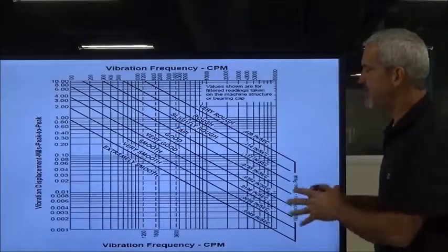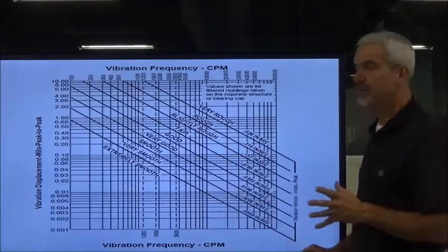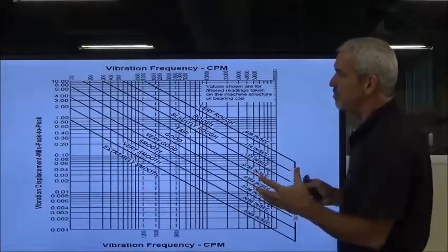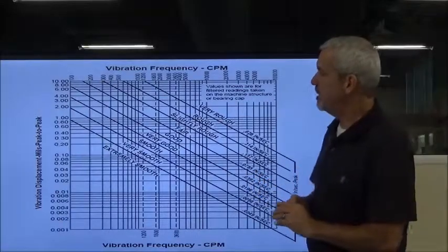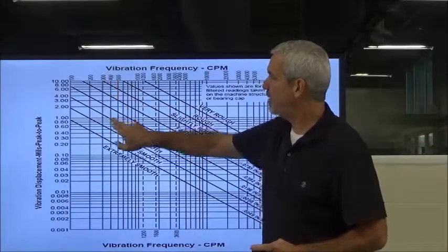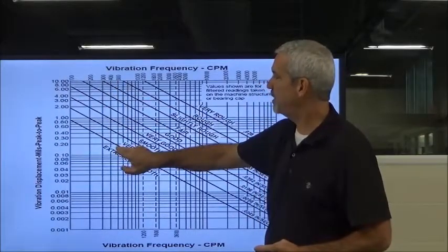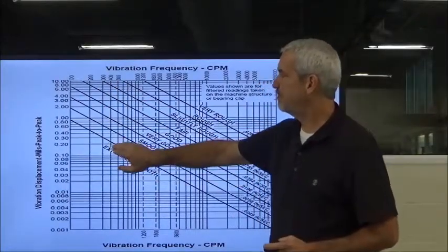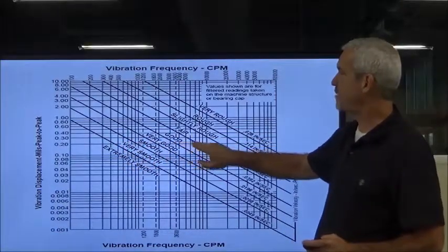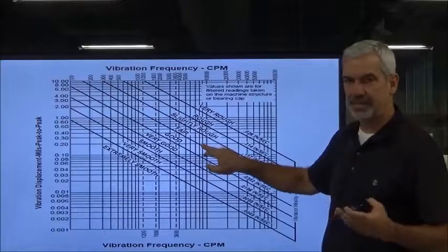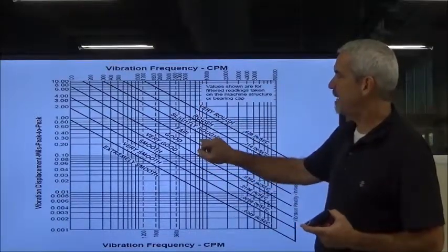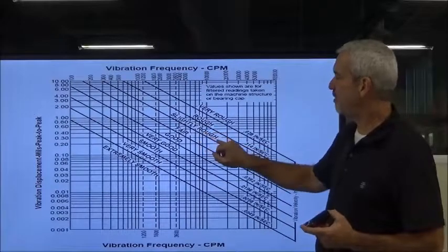And really, you're not going to see this, but I will hand this out in the mandatory in-person lab that everybody's going to be coming to. What this does is give us an idea of how, whereas it might be very smooth running at 400 or 500 RPMs or cycles per minute, that vibration might be considered very smooth. However, if we run it at a much higher RPM, for example in a lathe or something like that, then we're looking at this being in the slightly rough category.